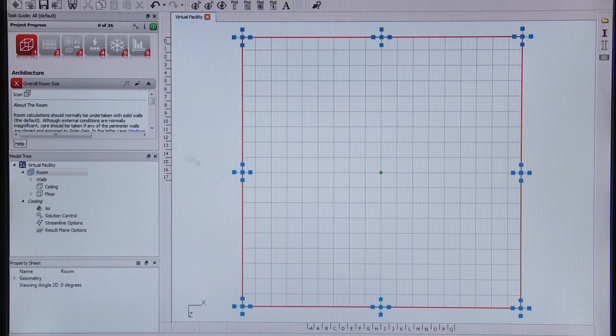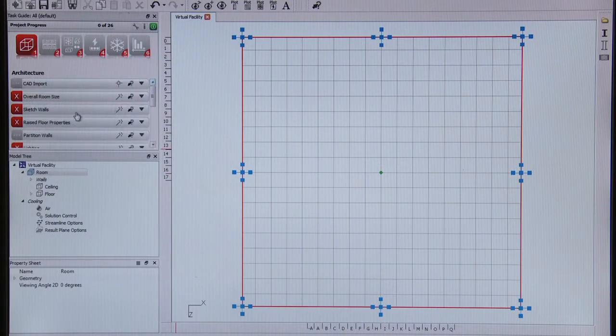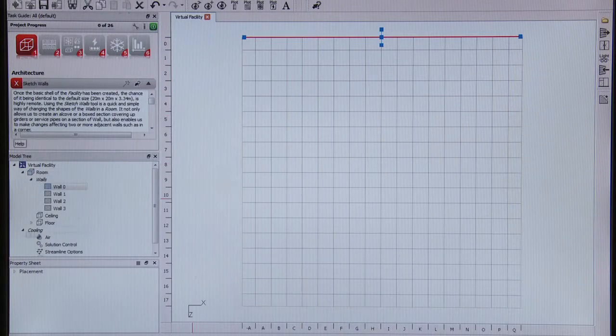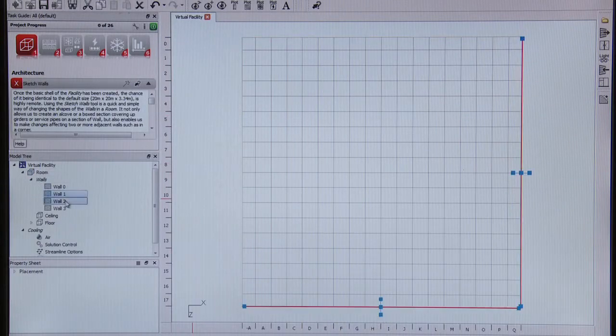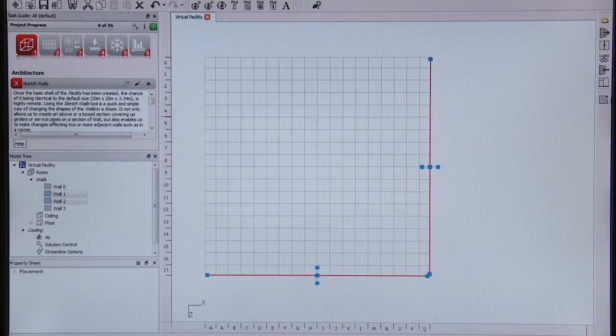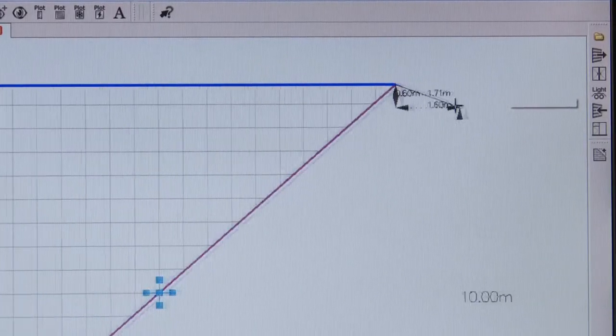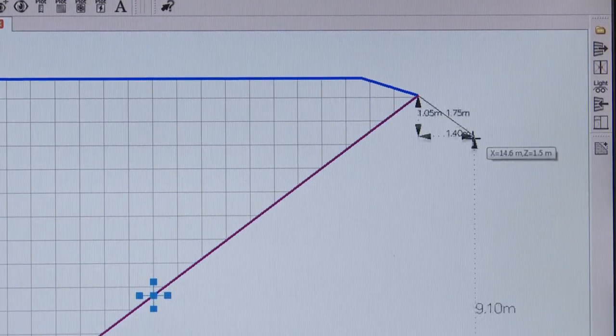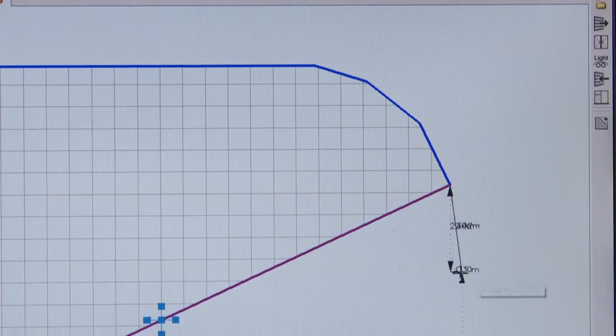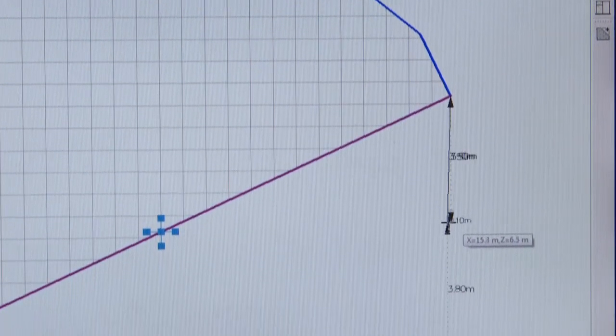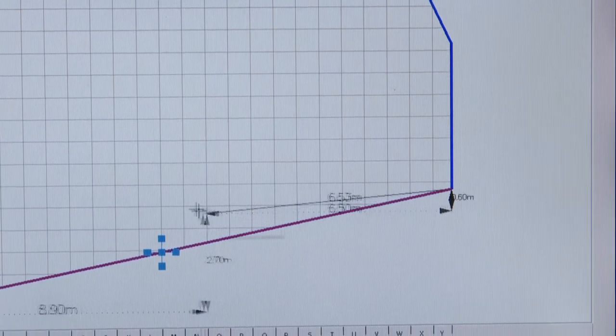The first thing you need to do is to create the model of your room. So that means we need to look at the size and shape. You can simply drag the handles to make the correct overall size, and then with a few clicks we can sketch out where the walls go to get the complete room's shape.